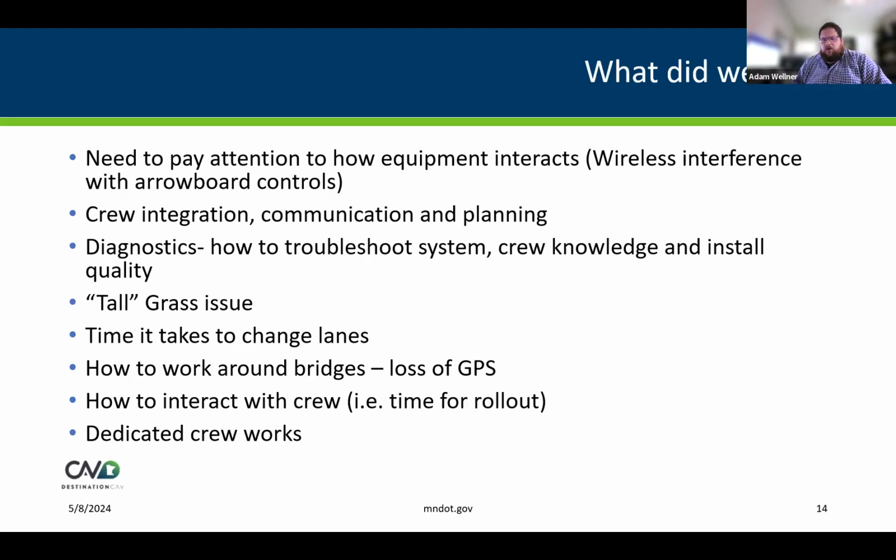And we were having a weird problem anytime we changed the message on our aero board. Well, we did some research and found out that the controller for our aero boards happens to use the same frequency band as the equipment the vendor provided to connect these 2 trucks. And so it looks like we were probably getting some interference there. And we've learned we can cycle the frequency that aero board uses and push it to a little different area of the band it allows.